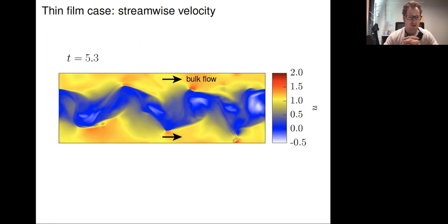My question is the mean question that I always ask everyone when I see work in this area at conferences, which is that we know linear stability theory does a really bad job at predicting ligament and droplet size in these kinds of flows, because like you said at the beginning, the initial Kelvin-Helmholtz or Rayleigh-Taylor type instabilities bear no relation to the size of the droplets that you end up getting. So there's a disconnect there. The question is, and this is a hard one to answer, I guess, is there any hope for nonlinear global stability analysis in these kinds of problems, given the huge computational cost of doing a simulation?